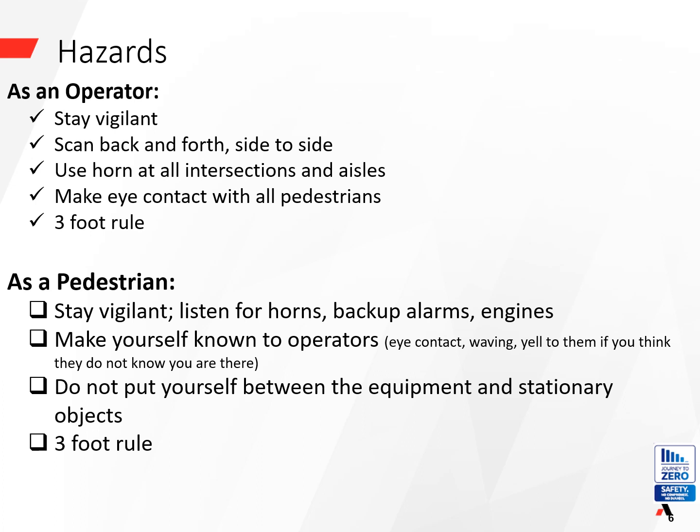As a pedestrian, remain vigilant and attentive, listening for horns, backup alarms, and engine noises. Make yourself known to operators by establishing eye contact, waving, or yelling at them if necessary. Avoid placing yourself between the equipment and stationary objects to prevent accidents. Adhere to the 3-foot rule, always maintaining a safe distance from operating equipment.